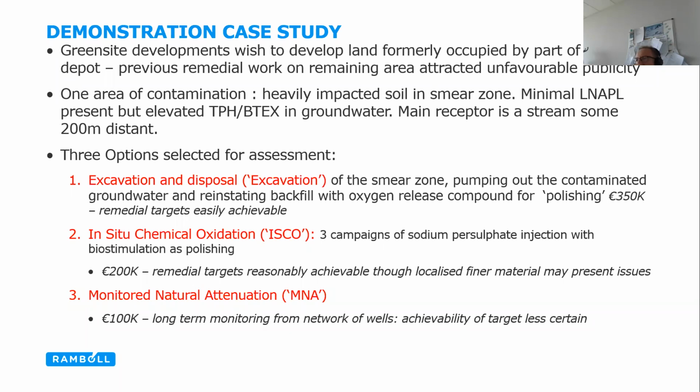Three options are selected for assessment: excavation and disposal of smear zone soil, then pumping out the contaminated groundwater and reinstating with clean backfill, including an oxygen release compound for polishing. We call this excavation. We've estimated this to cost about €350,000, but the remedial targets are easily achievable.